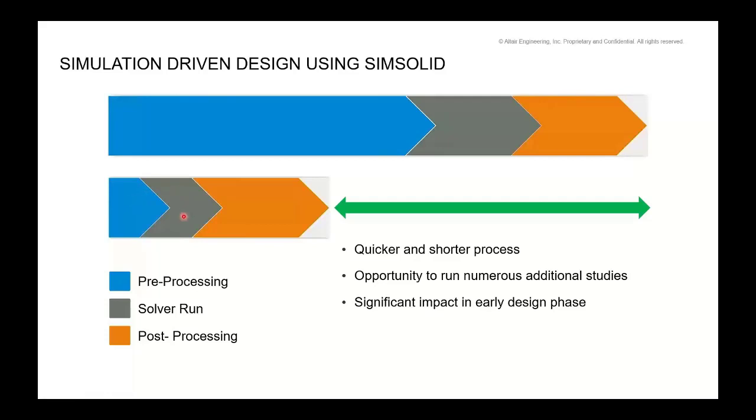The solve itself, because of its new technology and the type of elements it's meshed itself with in the background, what the solver does is apply high-order differential equations on the different parts of your structure in order to calculate the stresses, strains and displacements at those different parts of your CAD. So that's the technology behind it, and that's different to the traditional F equals KU sort of formula that we're looking at.